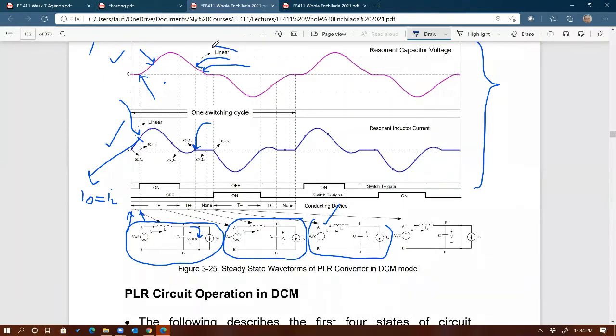So that's why I put linear right there. dV/dt is equal to I out over C. So that's why it's a constant rate, decreasing voltage, until the capacitor voltage goes to zero, until we deplete all the energy inside the capacitor, at which time the diodes across it are ready to conduct current, forward biased. And that's when the circuit transitions to the next one.